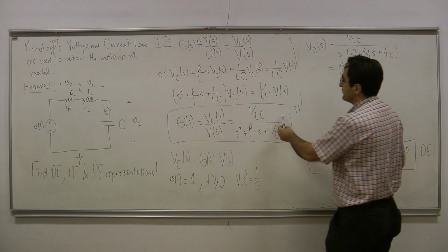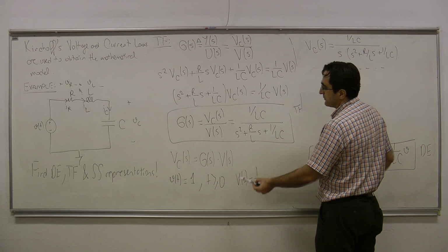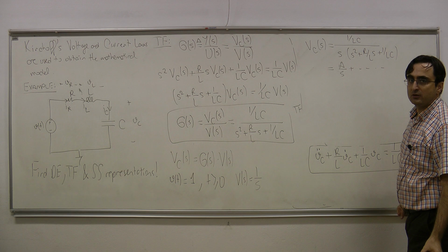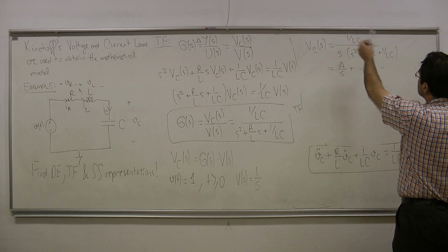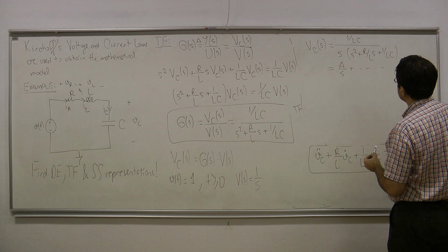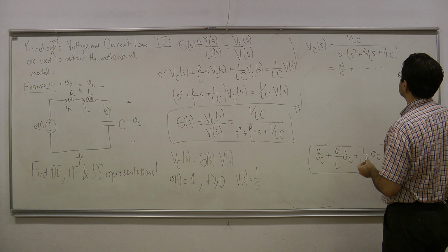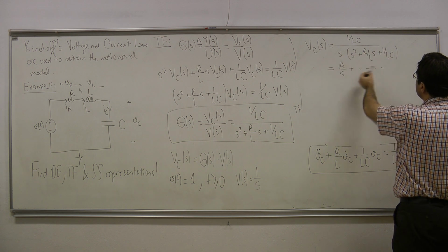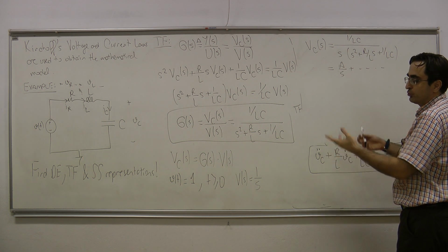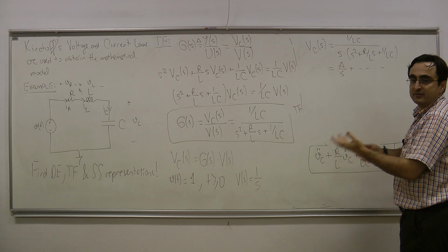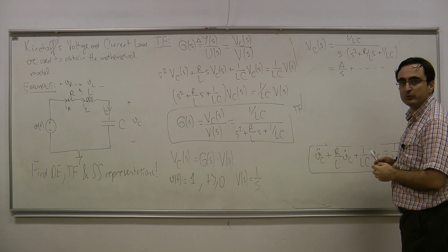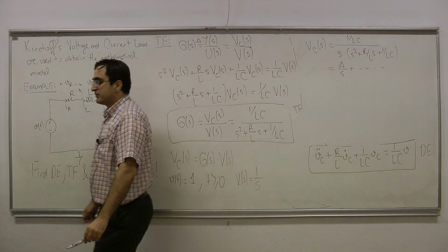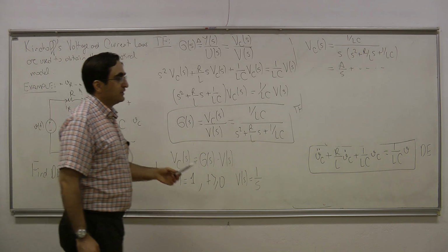So by just knowing the transfer function, I can multiply that transfer function with the Laplace transform of the input, and then I know the Laplace transform of the output. All right? And I can try to understand the characteristics of that output by looking at the poles of that Laplace transformation. A pole at 0 means a constant, and double poles at some locations mean either two exponentials or sines and cosines with exponentials in front. Okay? So this transfer function idea lets us understand the behavior of the output for different input types.